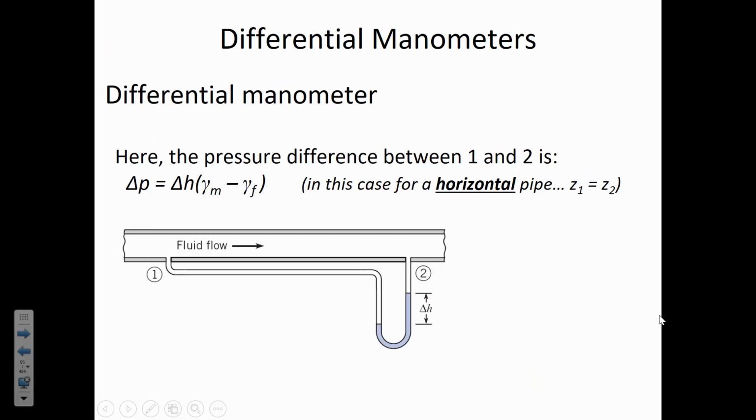All right. So a manometer that's open to the atmosphere is what we just saw. Another type of manometer is one that connects both ends of the tube to a pipe that it's measuring the pressure in. And so it's called a differential manometer because with a differential manometer, instead of measuring the pressure relative to atmospheric, you're using it to measure a pressure difference within a pipe. So you'll notice that this manometer is connected to the pipe some distance apart. One of the taps is upstream, one of the taps is downstream relative to the direction of fluid flow.